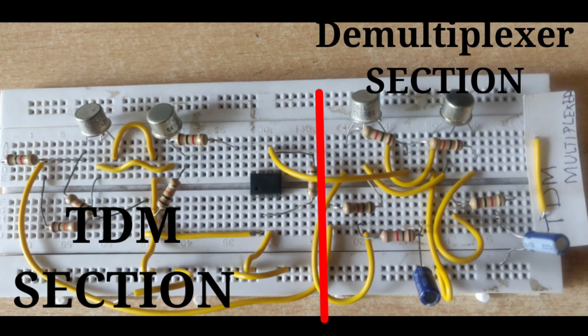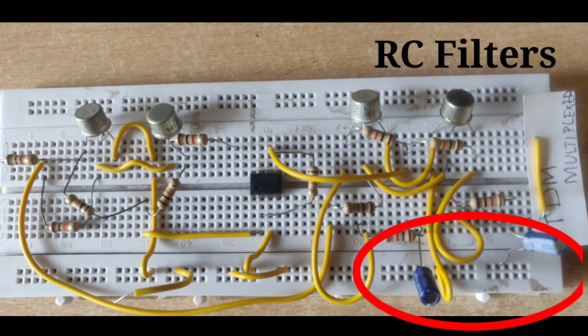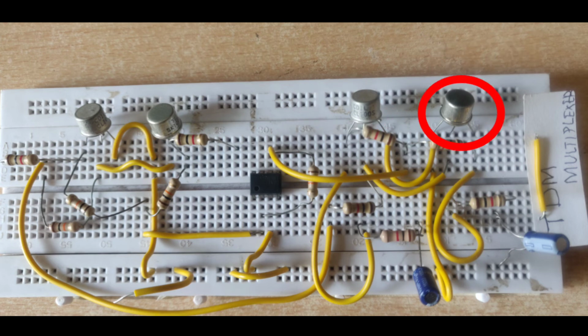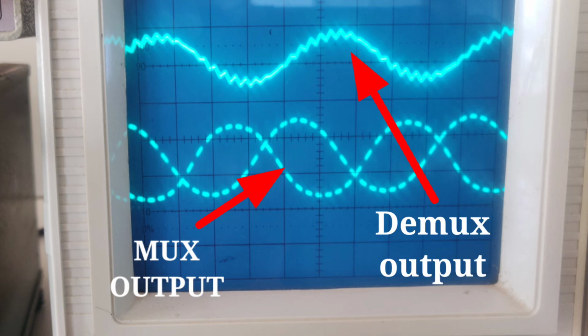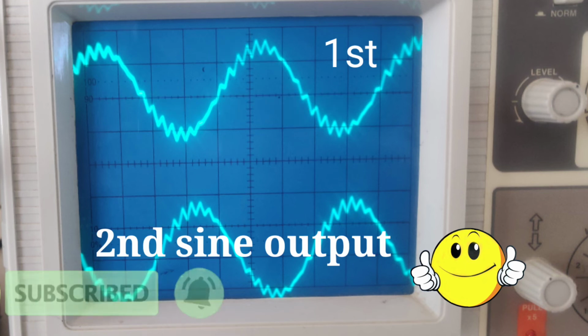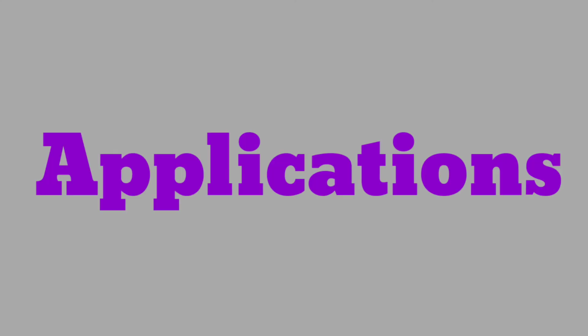So this is the circuit prototype I assembled on the breadboard, and see this part is an RC filter where we will get the output. There are two transistors in the demux section also. One is SL100 and one is SK100, and the switching circuit should synchronize so that the input switching square waveform is fed to the demodulator. See the demux output on the top of the CRO, and we have displayed here the two modulating signals, signal 1 and 2, and the demodulated output.